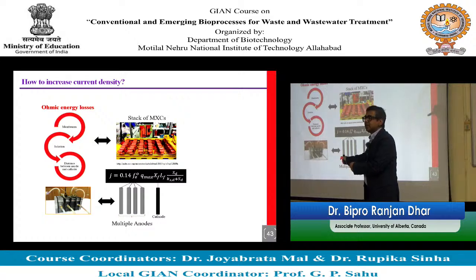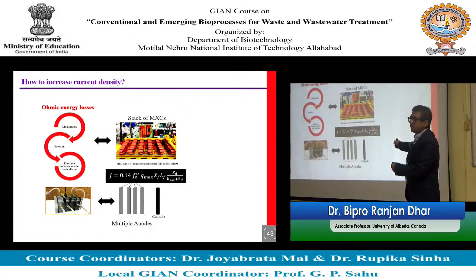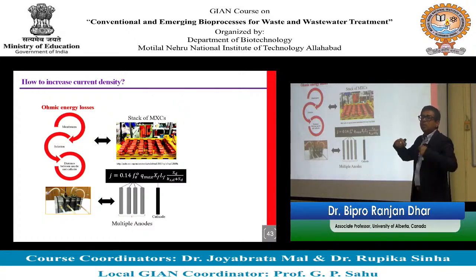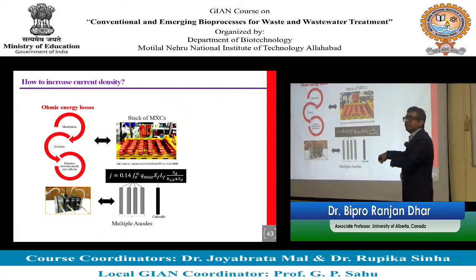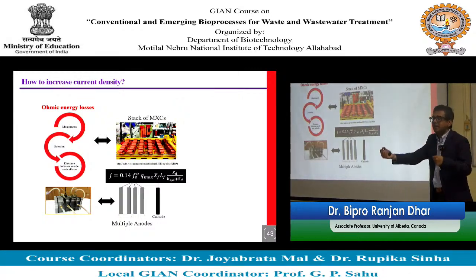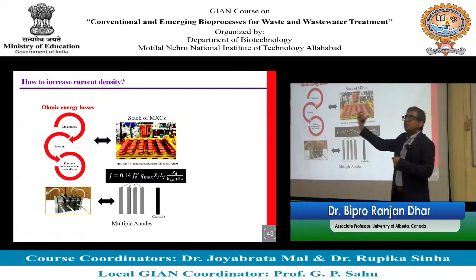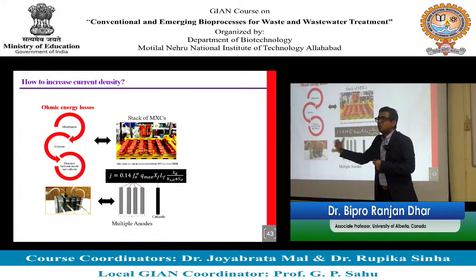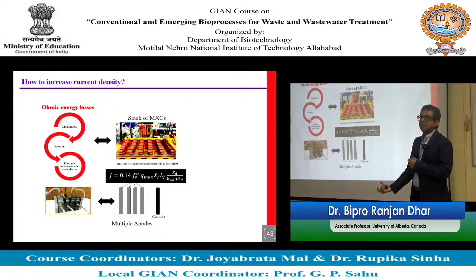As you can see, this is an emerging topic, but we can still use the Monod equation and apply that to estimate current density, which is our interest. But when we used the Monod equation to develop design equations for the activated sludge process, we tried to predict effluent concentration and biomass concentration, right?